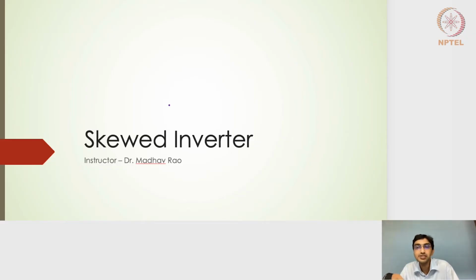So, given the input voltage, those intersection points gave us the current as well as the output voltage values. Those points were then put into the transfer characteristics, with Vout on the y-axis and Vin, the input voltage, on the x-axis, and thereby the transfer characteristics was drawn for the CMOS inverter. This is what we had seen in the last lecture.